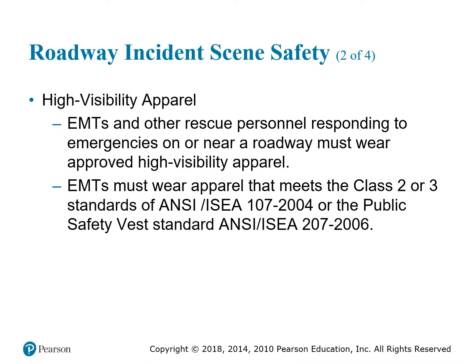High visibility apparel. EMTs and other rescue personnel who respond to an emergency on or near the roadway must wear approved high visibility apparel. EMTs must wear apparel that meets Class 2 or 3 standards of ANSI/ISEA 107-2004, or the public safety vest standards of ANSI/ISEA 207-2006.